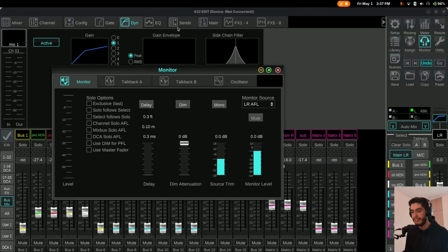And nothing can get above 0. 0 is the clipping point, which means if something gets louder than 0, it just gets chopped off. It cannot get any louder than that. -18 dB full scale is the nominal level, or it's the level that the gear expects to work within.